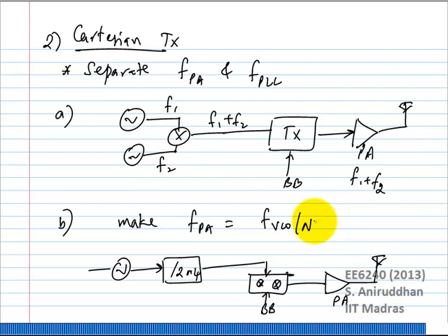Now, the other reason why this has become a very popular choice is because the divide by 2 also gives you all 4 phases. Okay. If you design a differential divide by 2 carefully, you can actually get very accurate 0, 90, 180 and 270 degree signals, which you anyway need for your single sideband mixer. Remember, your single sideband mixer requires cosine and sine, but it requires the differential inputs for cosine and sine. So this has become very popular.